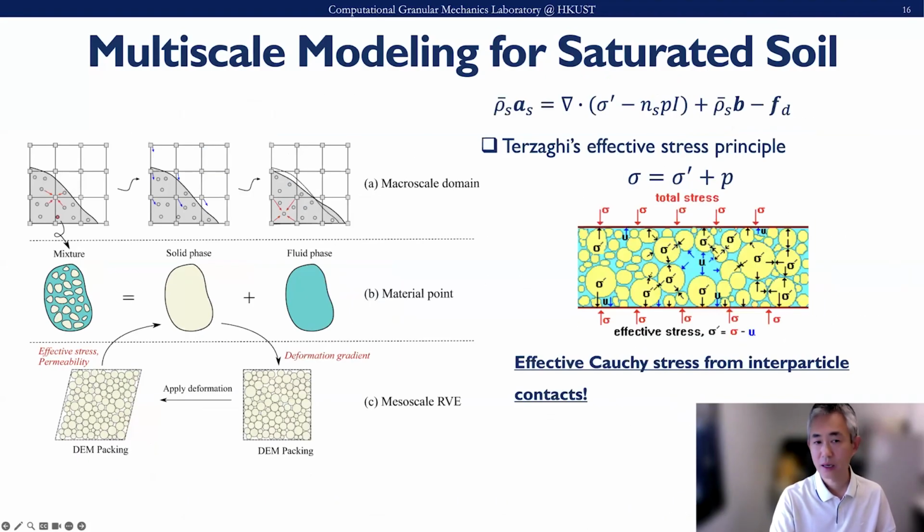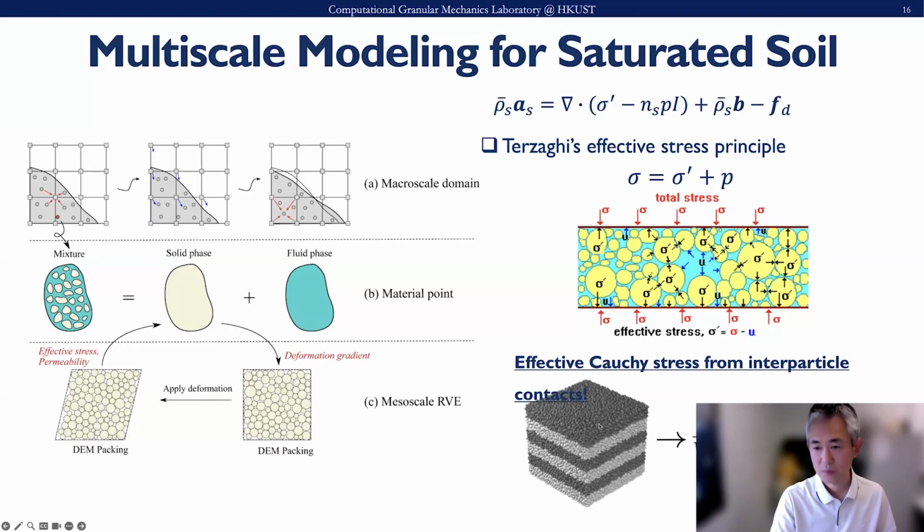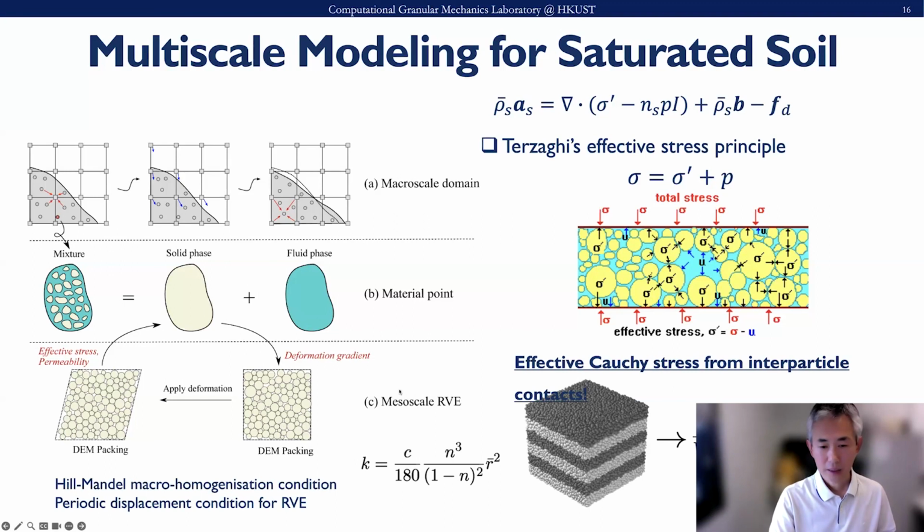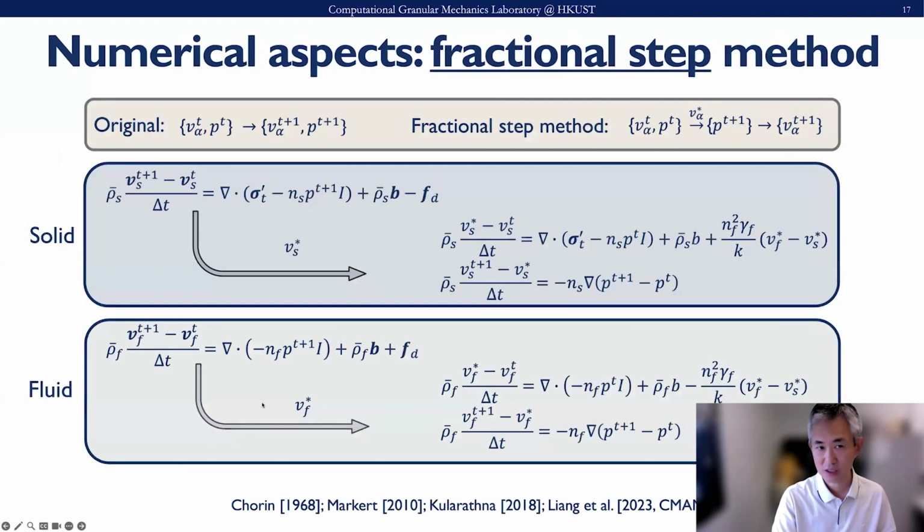Again, here we basically apply Terzaghi's effective stress principle for these particle-scale simulations, so that the DEM will return us an effective stress quantity by resolving all these particles and interparticle forces to form these stress terms here. Also, we can extract other microstructure quantities like permeability from this DEM simulation.